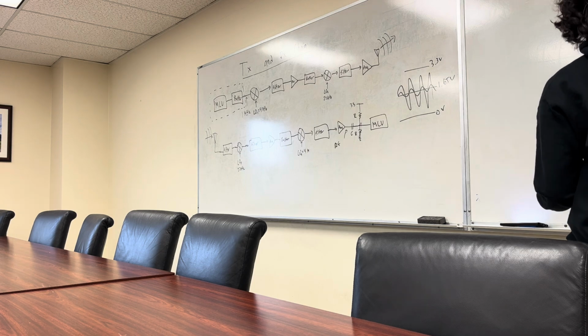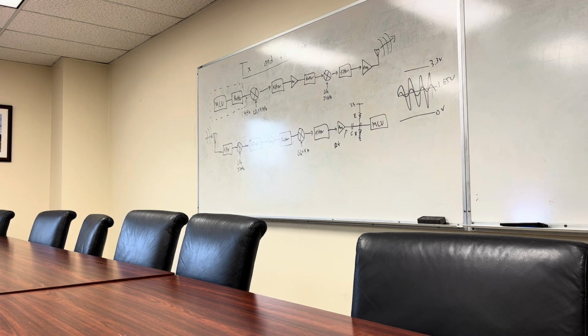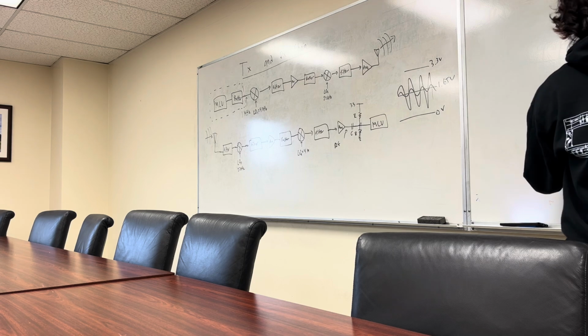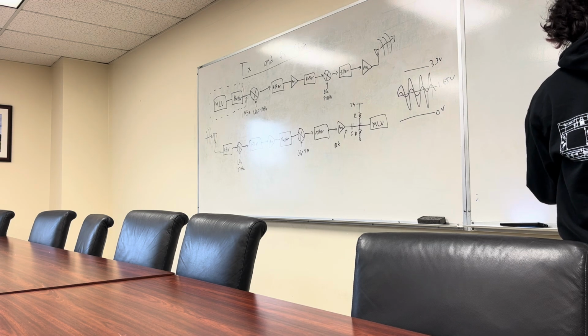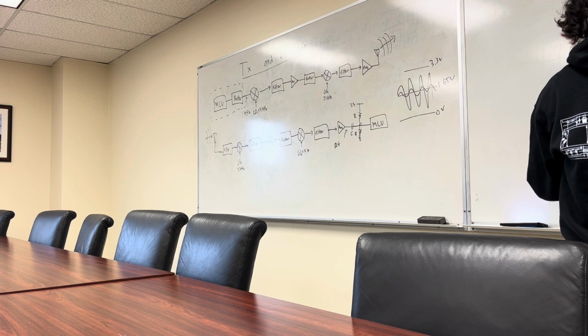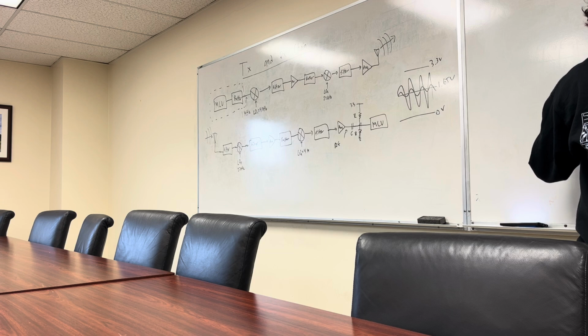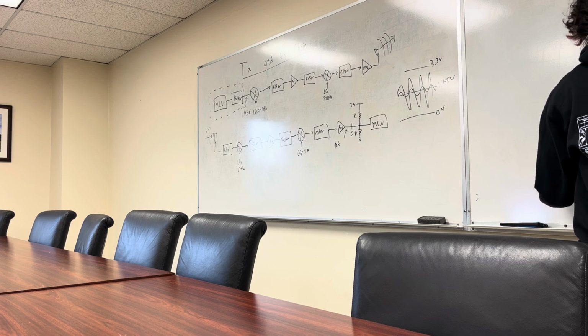And if you were to look at this from the perspective of our actual diode ring mixer, this is like our RF output, and our IF is here, assuming ground over here. This is our IF port here. You're effectively saying, okay, let's hook this up to some 1 megahertz source with a 50 ohm source resistance here, right? That's what we said.